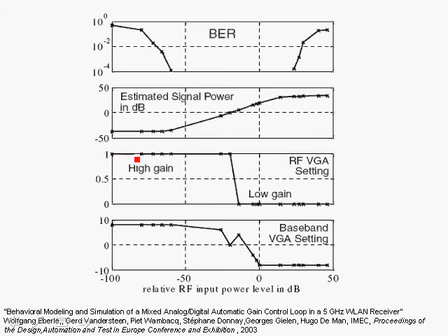As the signal to noise ratio increases, we're in the high gain, and at a certain point we begin to exhibit saturation. The baseband AGC control will detect that the RMS has exceeded a certain threshold, and instruct the RF variable gain to switch to the low gain, and this is what we see over here.